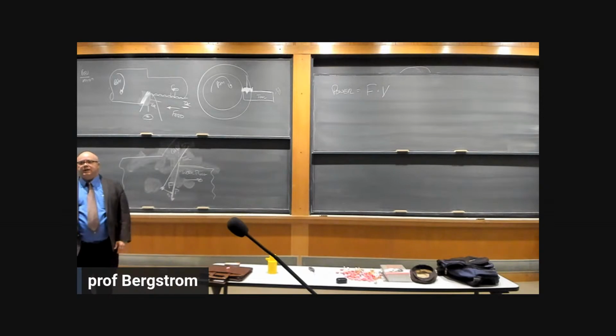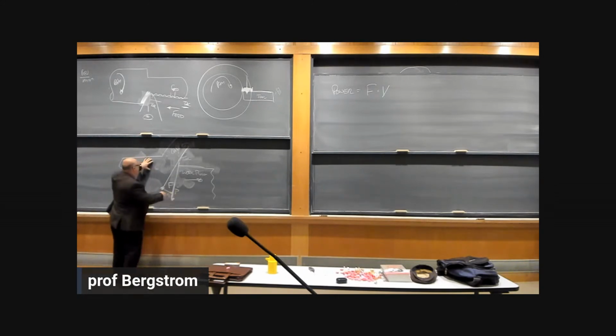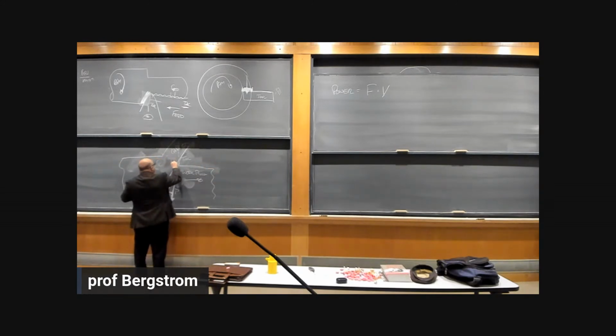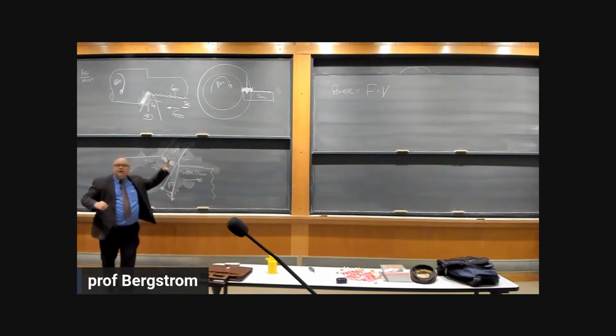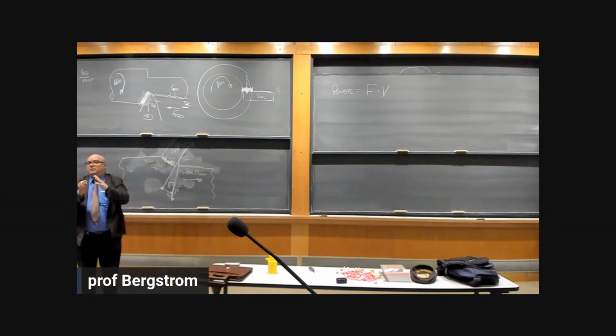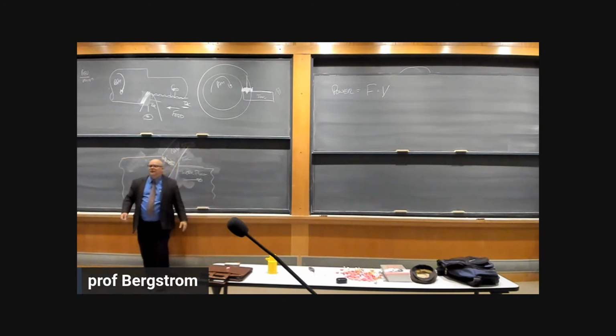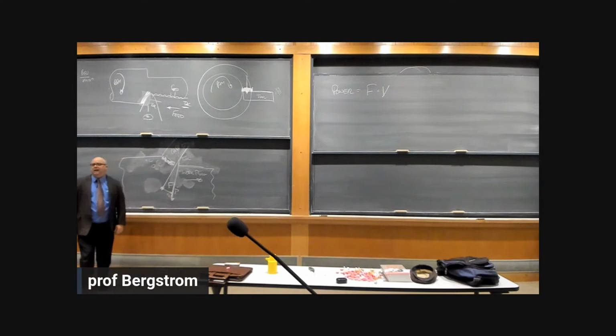We know the velocity of the chip is not the surface speed because we're mushing material together to make that chip. Right? We saw the video last week where we had workpiece material with all these different grains in it, all sort of symmetrical, and we move in this direction towards the tool. And then in the chip, the grains all look sort of like this. So we're taking energy and mushing the material together. It's going to slow down that chip as it moves out. We don't know how much it slowed it down.